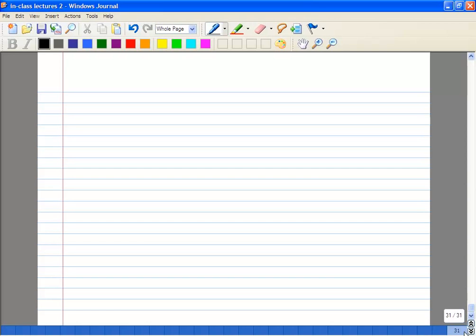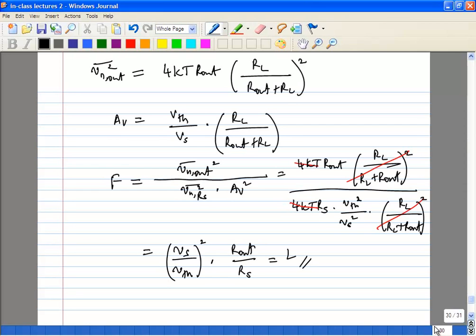So in this case, suppose we had an SNR of 9 dB perhaps at the input of the filter. And this filter has a noise figure of perhaps 3 dB. So SNR at output will be 6 dB. Yes, plus whatever attenuation it gives to the signal. No, but the difference is both the signal and the noise get attenuated. So if you have a certain noise at the input, that also gets attenuated through the loss, right?